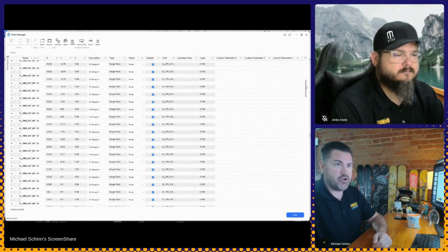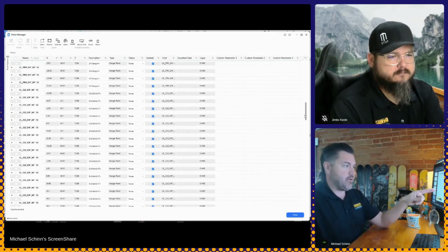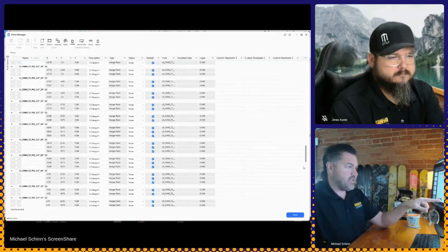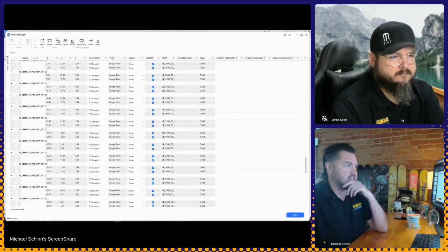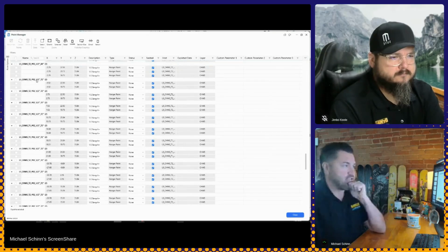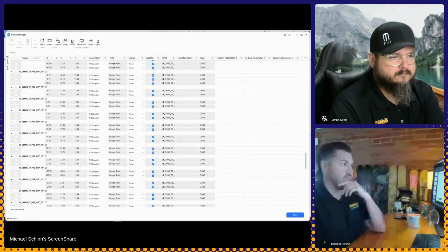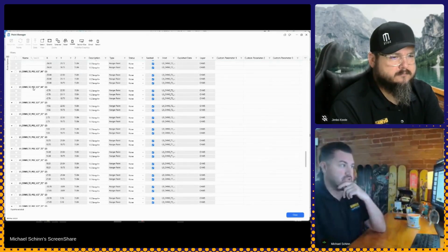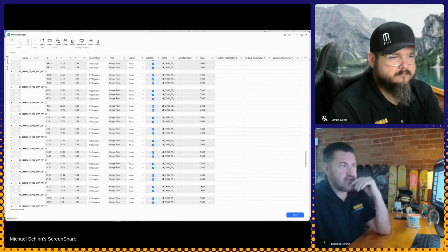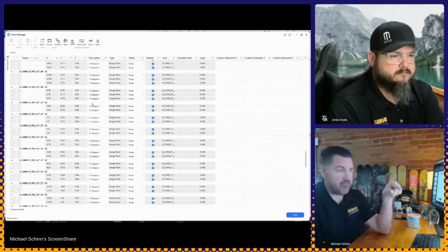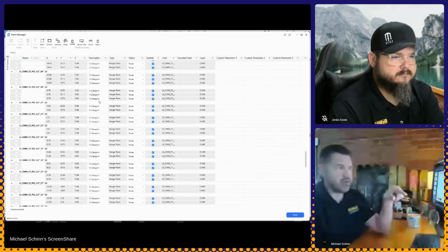So if I scroll through here, you can see every hanger name that we have on here with every point, even as you get down to the trapeze and the tier 3s and the tier 2s. So there's that hanger and then with the 2 points inside of it. Here's that other trapeze with the 3 rods and those points inside of it. X, Y, and Z, these can easily be moved around to change what order you want them to be exported as. For our hangers, it automatically fills in the rod size and the upper attachment.